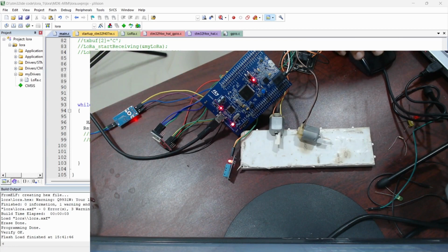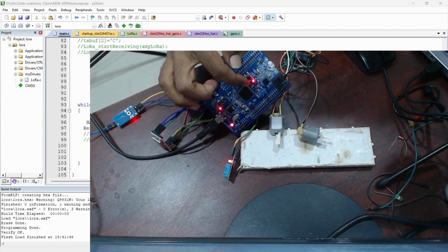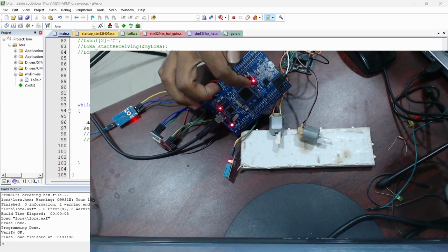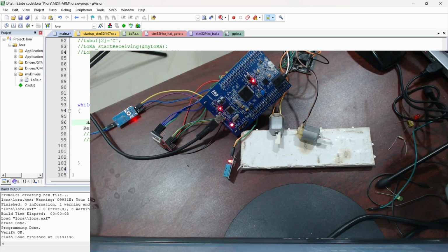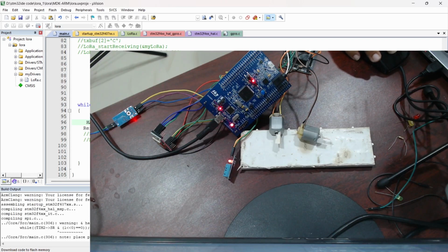So you can see this is our red LED, which is connected with the pin PD 14. Now you can see we have refreshed this watchdog timer before it reaches the timeout, which is 20 milliseconds. So we will change this scenario. We will make it as 25. Now I'm not going to reset this watchdog timer before it reaches the timeout. So we will upload this code now.